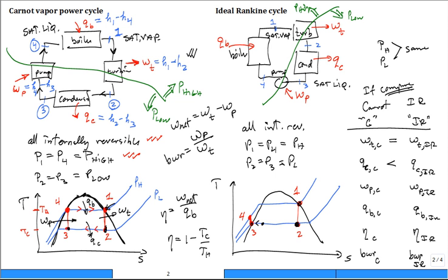What about the work of the pump? Well, that pump was a very special pump in the Carnot. It really doesn't exist, but to take 2-phase and boost its pressure is going to do a whole lot of compression on that. It's going to be very expensive in the Carnot, for a pump to do that. So the pump for the Rankine is much smaller.